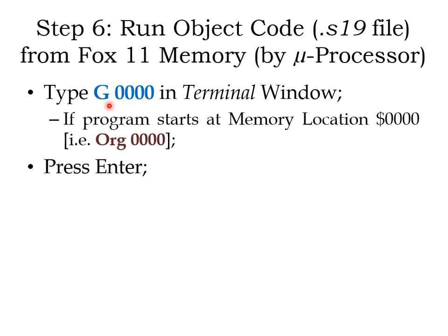But here is another example. Let's say if in your original program you see something like ORG 0000, that indicates that your program has actually started from the 0000 location, right? Then your run instruction should be this one. Do you see the changes?